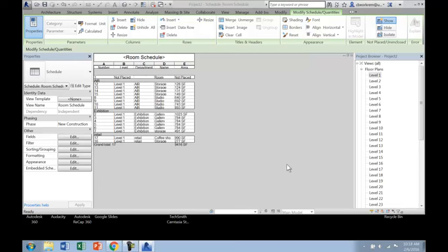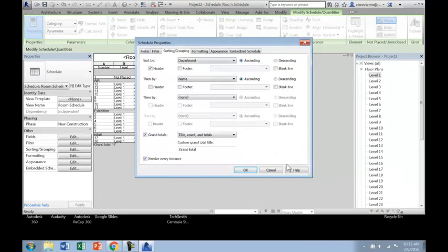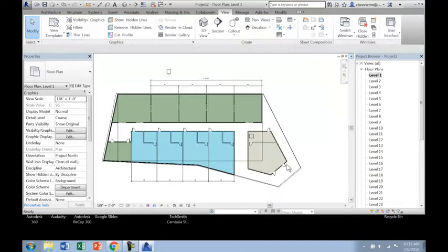okay, sorry about that. So just to get each of the departmental totals under the sorting and grouping, you need to add a footer in under the department to actually get those totals calculated. So here we're getting, so that room number, I need to go back and look at the first room number. It didn't get tagged as a gallery space. But you can see now I've got my 3,500 square feet of artist in residence space, 4,000 in exhibit space, and 1,200 in retail space, and then my grand total for that given floor plate.